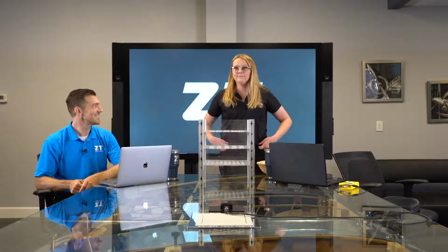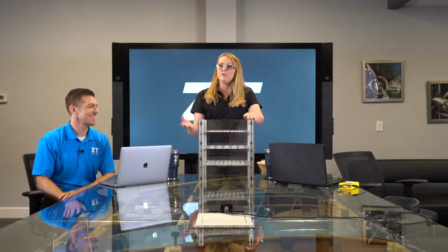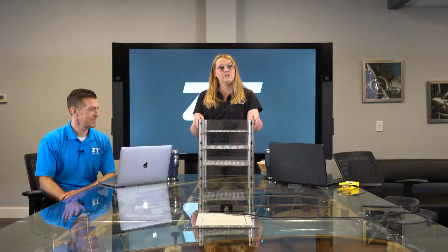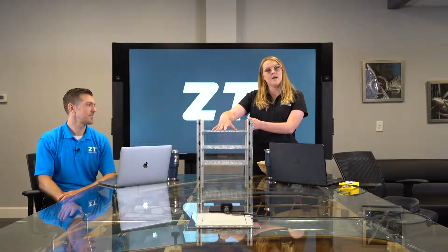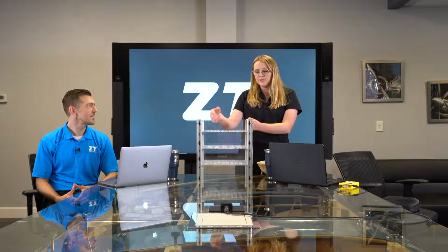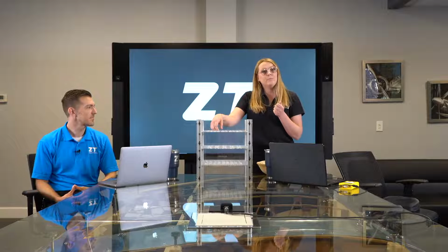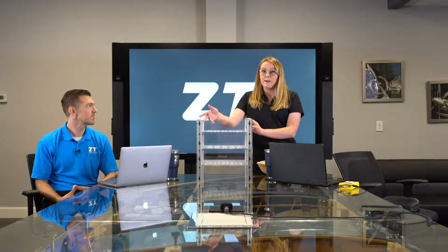Yeah. So this is our fixture. This is going to represent different shielding materials, and we're going to see how various materials work to shield different frequencies. So our top level here is going to mimic a material that's got some visible openings, maybe some kind of a knitted wire kind of shield. The middle here is going to be something with smaller openings, maybe like a porous surface. You might not even see those openings, but they're there. This could be something like a metallized fabric.